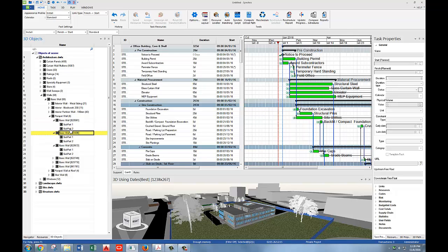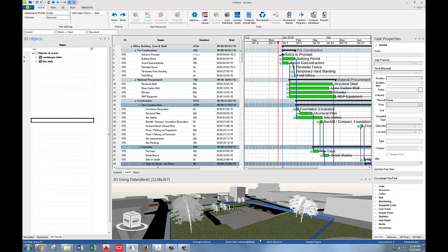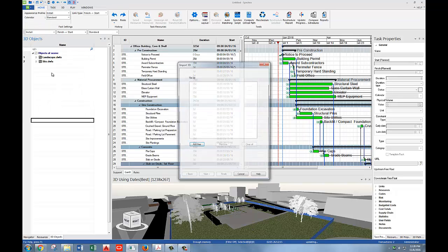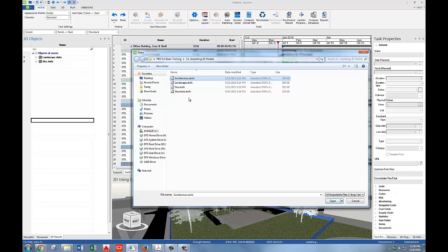And so if we count the number of tree levels that we are actually at, architecture is number 1, walls is number 2, basic walls is number 3, parapet walls is number 4, basic wall, the number, is number 5, subpart 1 and subpart 2 are on level 6. The unique identifiers stop at level 5, so that's what we would want our model to come in as, stopping at the unique identifier of level 5. So this is how we're going to fix it. Just hit undo, and that's going to unimport what you just did. Let's go through the process again. Add files, architecture and structure.